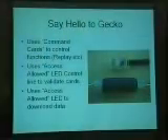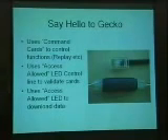And again, this is coming in V2, it uses the access allowed LED to get the data out of the reader. I'm using a PIC chip for this, and they're quite handy, because I can say, pin 5, you're an output pin, and you're currently driving that LED. Oh, you're now a serial port, 9600 bits per second, 8-1-no, and here, have this stuff to send.